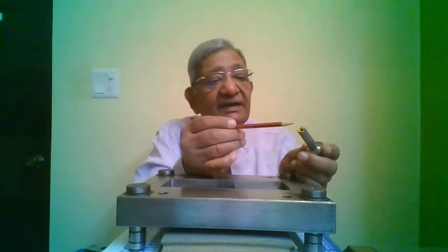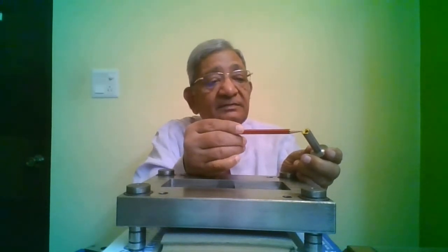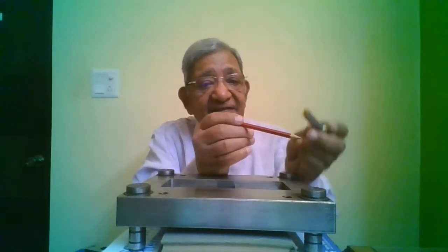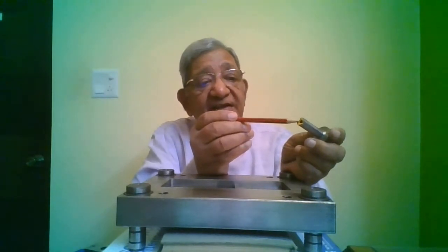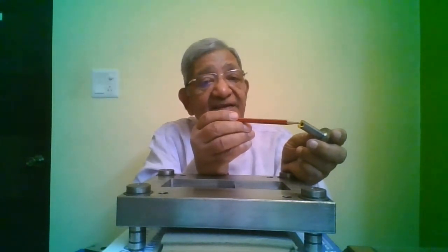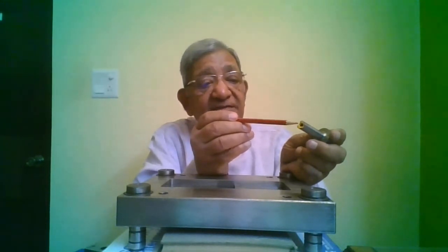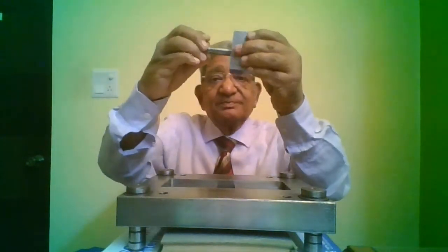And now you can also see that this end has got a runner channel as well. This is the runner channel. So the material will come out from this hole. It will travel through this runner channel, and this runner channel will align with the runner channel in the bridge piece. So you will see it, like I will assemble it. Now I insert this sprue bush.